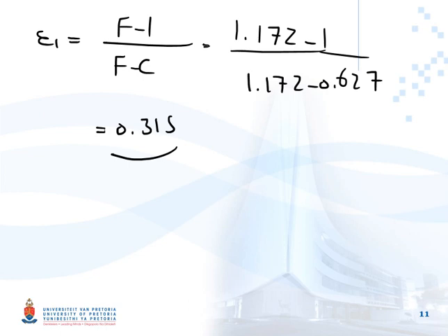Again, now we need to find the number of thermal units. If we go to the same table, we can find a correlation, but we need to keep in mind that the correlation can be used when we are dealing with an exchanger which has one shell pass.